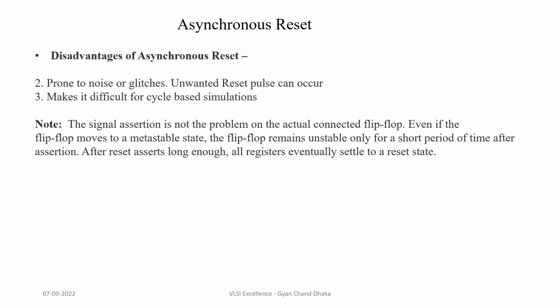Now, one thing to remember here is the signal assertion. As I said, signal assertion is not a problem on the actual connected flip-flops. Even if the flip-flops move to a metastable state, they remain unstable only for a short period of time after assertion. After reset asserts long enough, all registers eventually settle to the reset state, because the reset is going to be applied for quite some time. So asynchronous reset assertion is never a problem. The problem lies only with asynchronous reset deassertion.